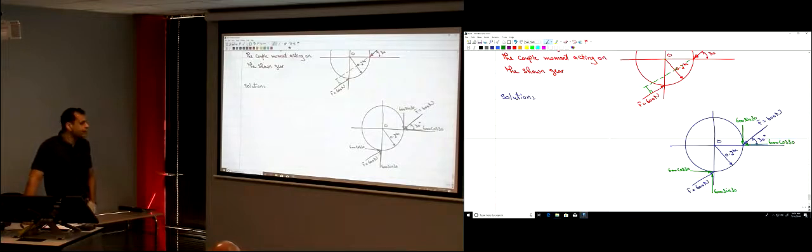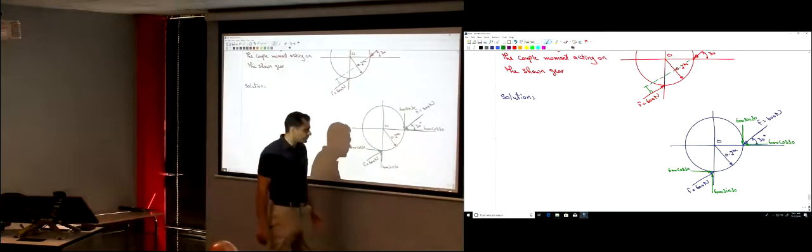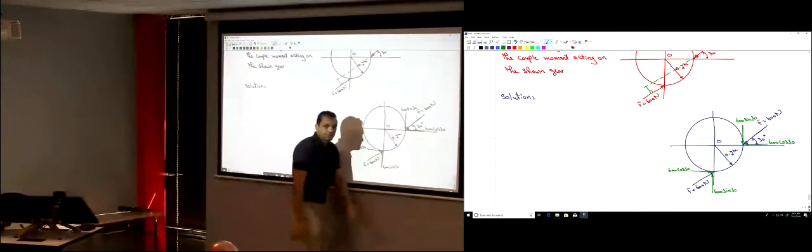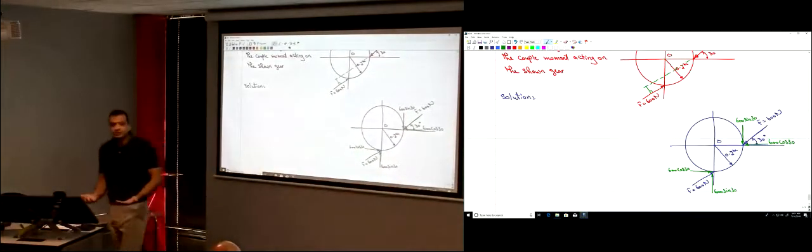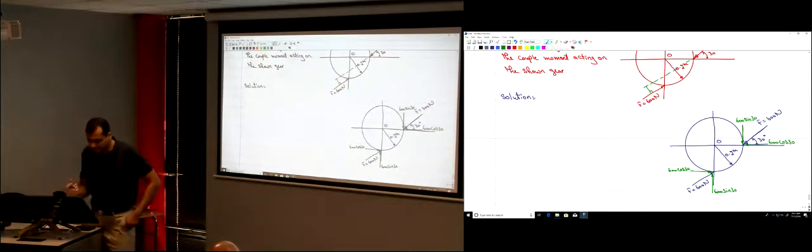So how many couples do I have now? A couple is a set of two forces that are equal in magnitude and opposite in direction. I have two couples: two equal and opposite horizontal forces, and two equal and opposite vertical forces. What did I gain from doing this? The distance used with each of those couples is easy now to use, right? How much is the distance for each of those couples now? 0.2, the radius of the gear. So that's easier now.